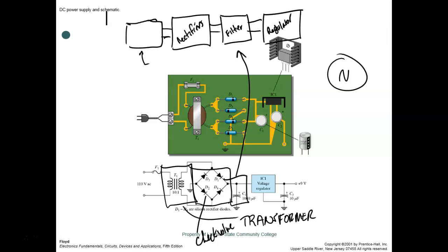Because how much EMF, how much voltage we get out of a generator is determined by one thing, it's the speed of the motion. Does your engine run at a constant speed all the time? Power varies with the square of the voltage. So you're sitting there idle and nothing would work. Your radio wouldn't work. When you got up to speed, everything would burn up, right? So we got to have a regulator. It's maintaining a constant output, right? You understand that? It makes your alternator put out a constant output.